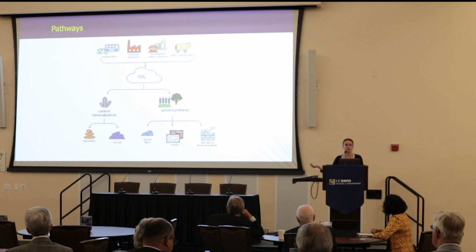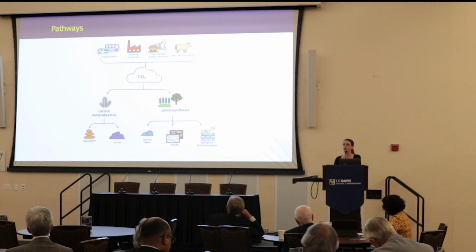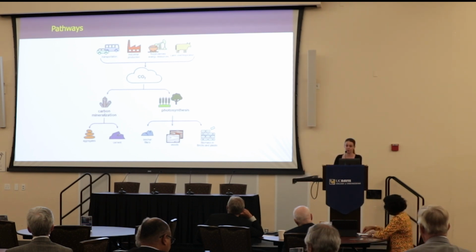Or can we potentially leverage biogenic resources? Biogenic resources tend to not be quite as long-lived because many of them have natural microorganisms available that can help break them down, whereas our mineralized structures can last a little longer. And we're looking at different ways of starting to integrate these into the built environment, including things like potentially solidifying our cement through carbonation as opposed to hydration, through the formation of synthetic aggregates, through the utilization of biogenic resources in concrete, as well as quite simply using biogenic resources as the components themselves in the built environment.